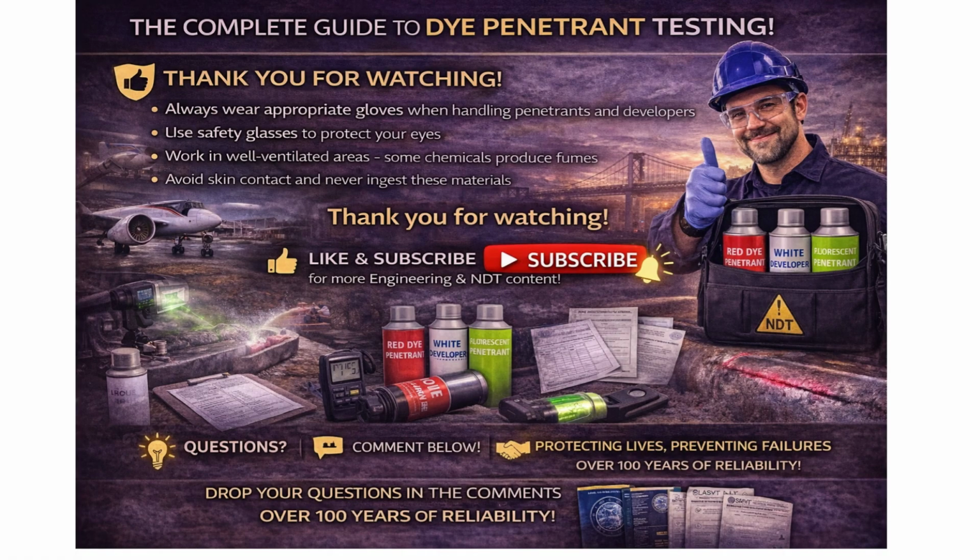And there you have it, a complete guide to dye penetrant testing. We've covered what it is, how it works, the 6-step process, its advantages and limitations, and where it's used in the real world. This simple yet incredibly effective method has been protecting lives and preventing failures for over a century. From the wings of the aircraft you fly in to the pipes that carry your water, from the cars you drive to the bridges you cross, dye penetrant testing is working behind the scenes to ensure everything is safe and reliable. The beauty of this method is that while the basic principle is simple: apply dye, let it soak in, remove excess, apply developer, and look for indications, the applications are incredibly sophisticated and critical to modern industry.